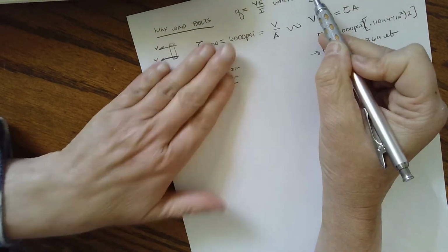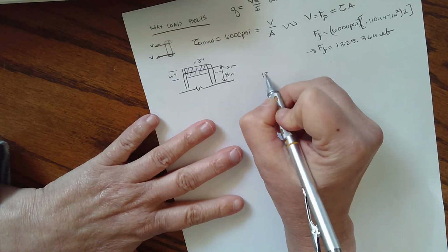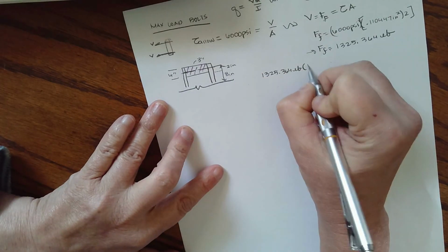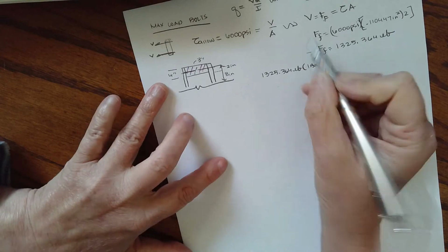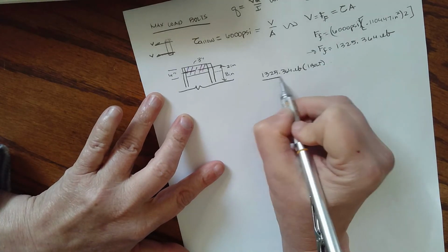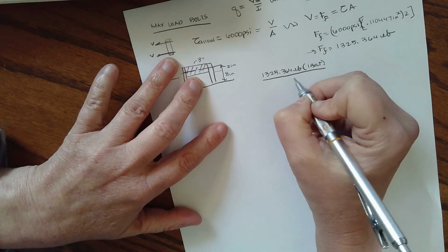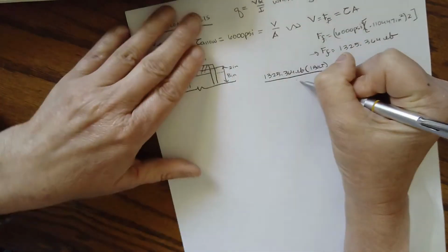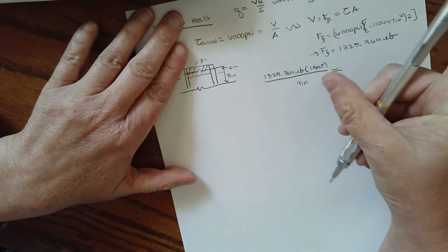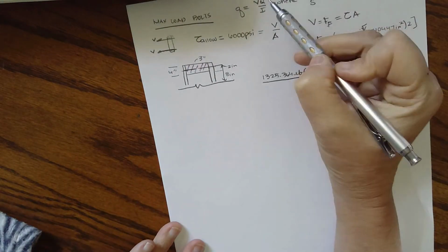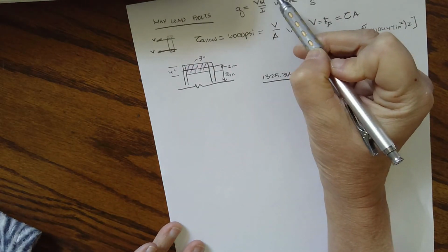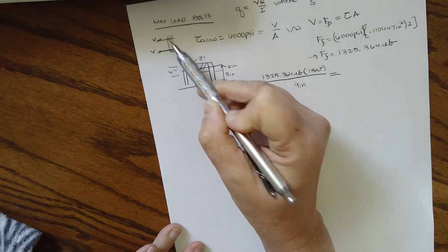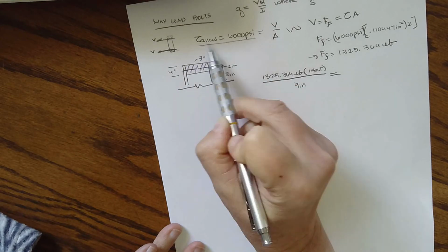So now we can put this all together. I have the force of a fastener, 1325.364 pounds. I have 1 bolt. I've already taken into account double shear when I found that capacity of the fastener, divided by spacing. Spacing was given back over here, 9 inches, equals, okay, V. This V is coming from our system. This is from our beam. This V was the shear force that would be the allowable shear force based on our bolt material, okay?